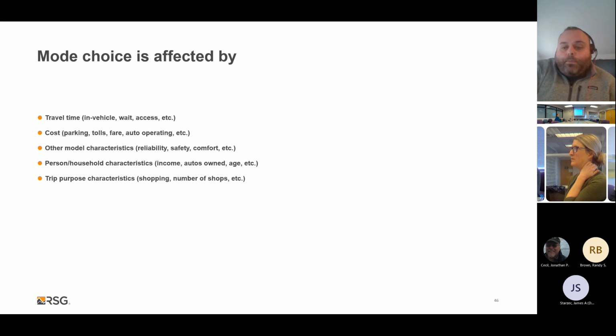So the way that I would approach it is that if you want to really get serious about modeling bike and pedestrian travel, then you need a standalone bike-ped model to do that, because there are issues with the travel demand model. The unit of analysis in this travel demand model is a travel analysis zone, and the travel analysis zone is too aggregate to appropriately model pedestrian trips. You can look at some of the zone sizes that we have in Anchorage, and they're huge. There are tons of pedestrian trips especially happening in the zones that we're not capturing.